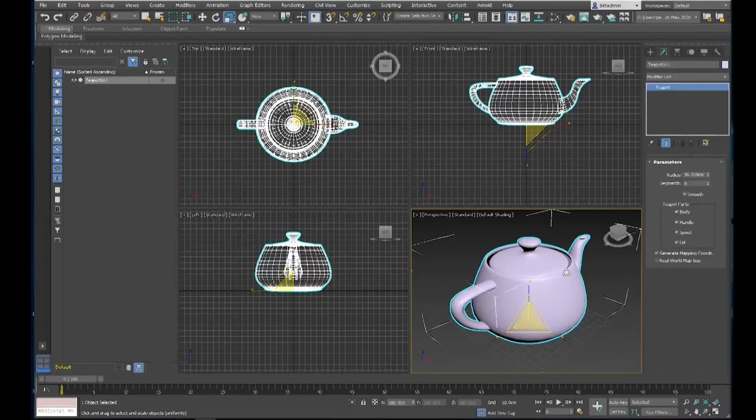And the third reason comes from the modeling itself, because every modeling tool has kind of a base level. If you are using meters, every modeling tool will offer you units in meters. But if you try to model just a hand or a small toy soldier, for example, meters for a toy soldier is way too big. So you will slow down. So please try to use proper units at first. Just a second.